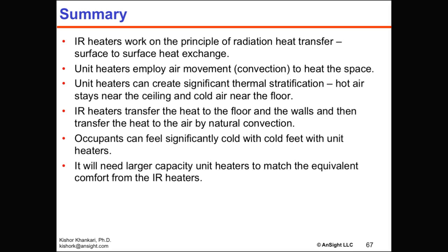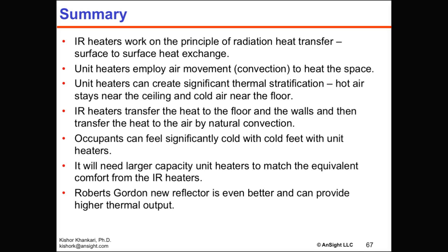With unit heaters, it will require much more heat input. You can say we put 200, maybe several 100,000 more BTUH with the unit heaters to achieve the same level of comfort we can achieve with IR heaters. Roberts-Gordon new reflector is even better. So you may not even need 200,000 BTUH to achieve what I have shown it to you. IR heaters provide you bigger bang for your buck.